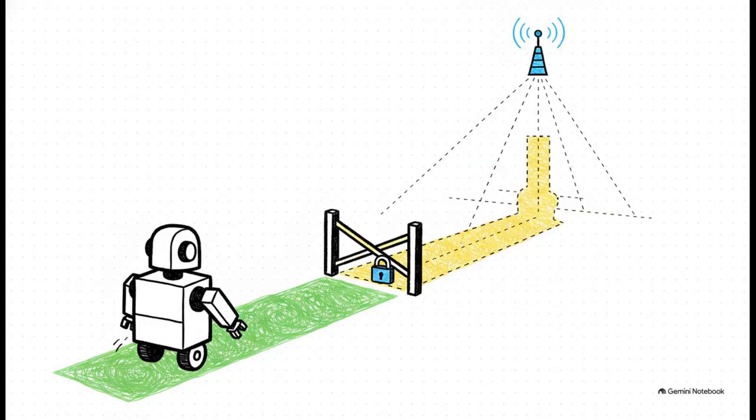Okay, so the master brain knows what the robots can do. Now we've got to actually manage their movement so these independent machines don't literally crash into each other. To handle this multi-vendor traffic, VDA 5050 dynamically partitions paths into two key concepts. First, you've got the base. This is the green-lit release ground that a robot is completely cleared to safely drive on right now. Second, there's the horizon. These are the upcoming path segments that the master control is deliberately withholding.